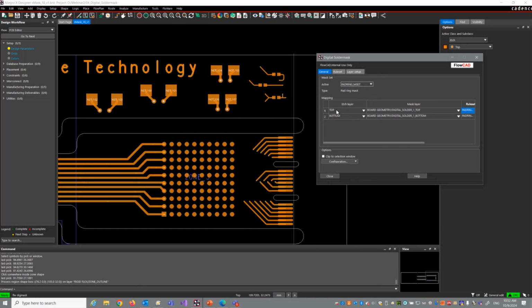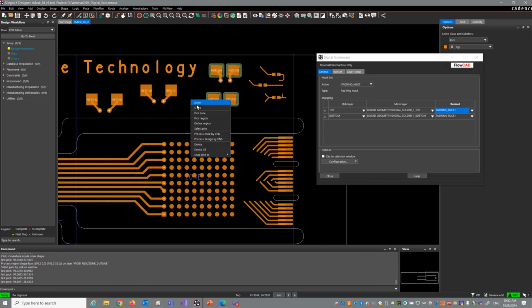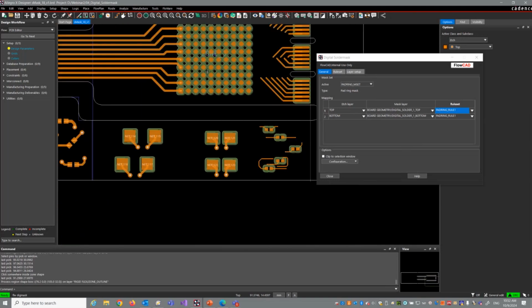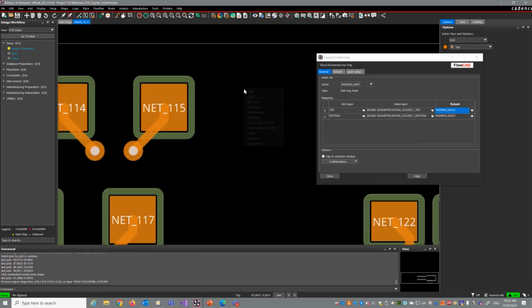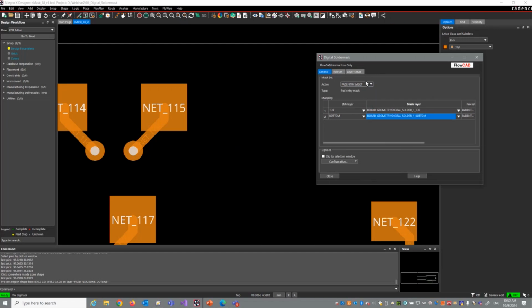Components or pads on the top layer will generate data on solder 1 top using pad ring rule 1 in this case. Again, I can select pins, like this one here, click here, click here, click here, delete all, or in a similar way, pick zone, click here, and now all the pins within that zone have been selected and a pad ring will get generated.